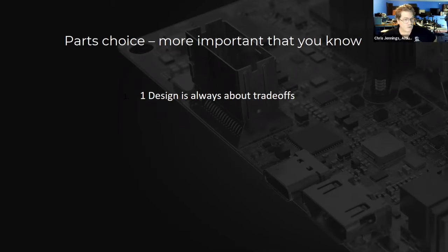So one of the trade-offs that you could make in your design is to say, well, let me look at the cost of a Bluetooth device with a built-in antenna. Or let's look at a Bluetooth module that has an SMA connector for an antenna built into it. So I don't have to do any impedance controlled routing on my board.